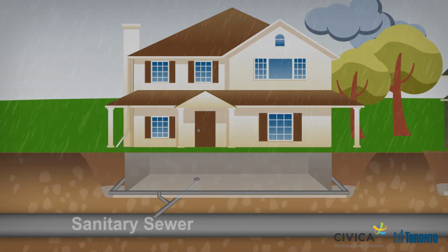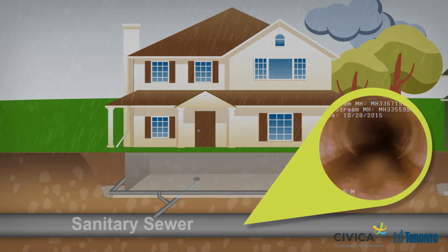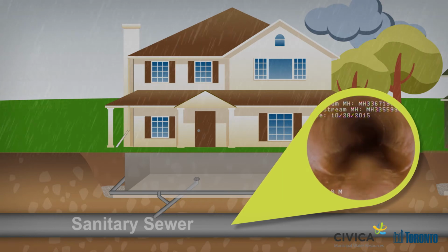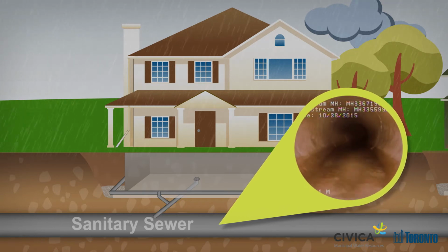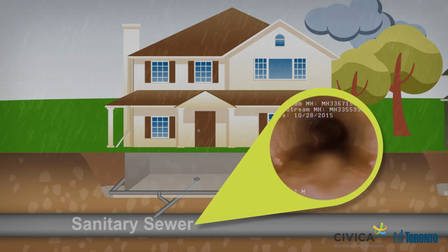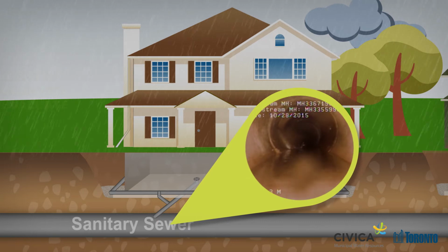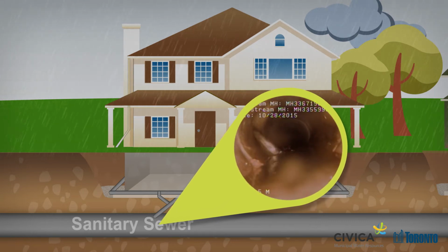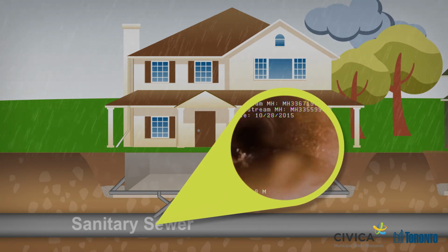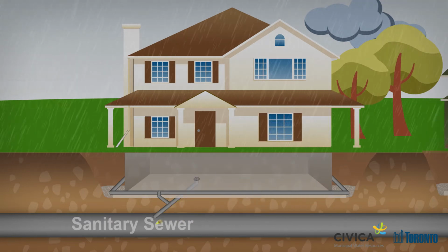The October 28, 2015 CCTV pipe inspection completed in the sanitary sewer indicated that the sewer pipes were in good condition under wet weather conditions, with no significant contributions noted from pipe defects. However, significant amounts of clear water were observed coming in from the sanitary service laterals. These service laterals corresponded to homes where records show foundation drains were connected to the sanitary sewer system.